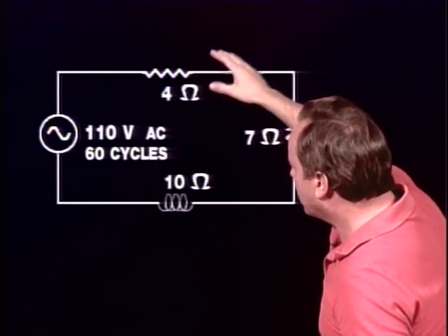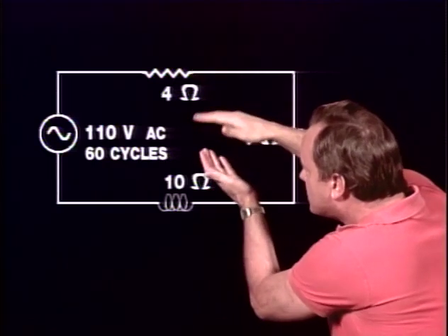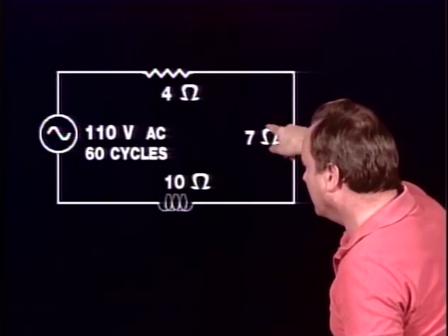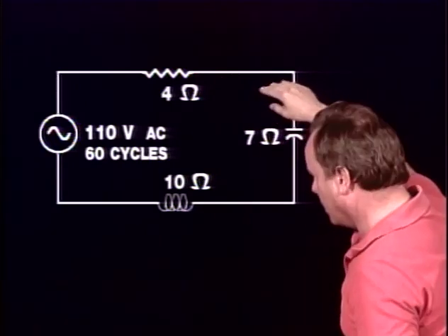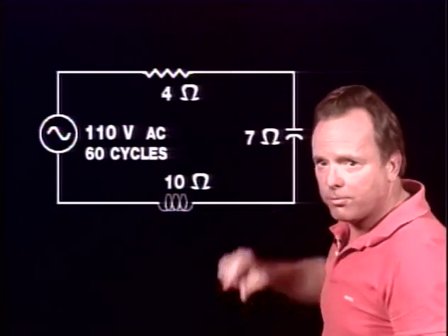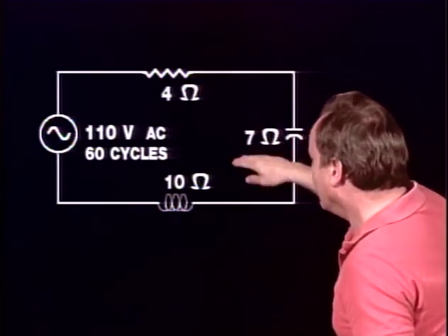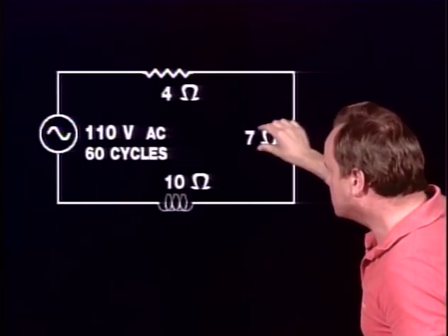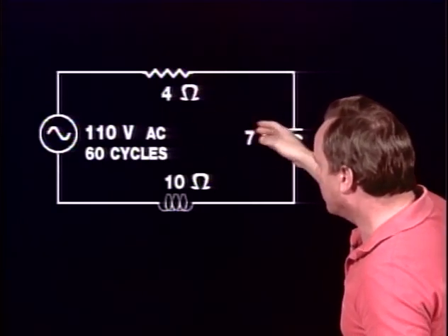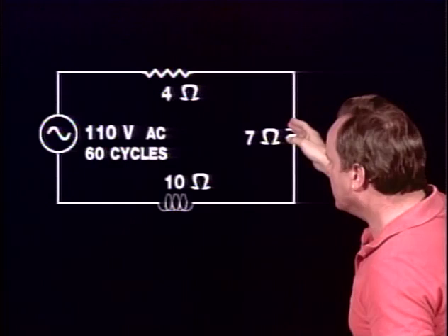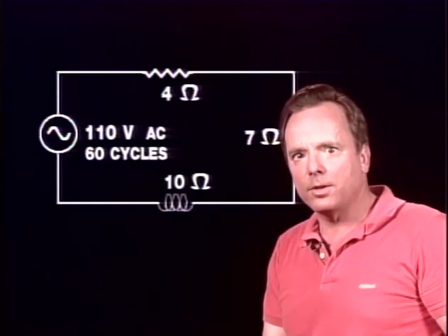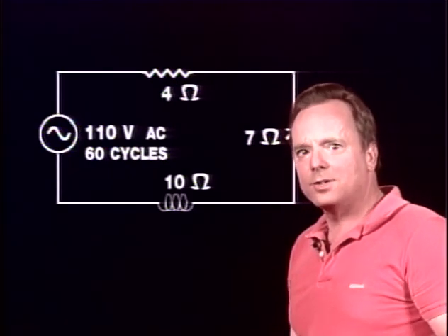But if the alternating current has a frequency to it, as the frequency increases, this capacitor tends to impede the current less and less because it charges the plate and it gives up its charge. Charges the plate, gives up the charge. And the faster the current changes in frequency and direction, in other words, the higher the frequency of the current, the less impedance is imposed by this capacitor here. And by the way, since the capacitor is almost like a short at first, it gives a place for the current to go, what happens is the current is about 90 degrees ahead of the voltage. Now in inductance, remember that the current's about 90 degrees behind the voltage, and this is going to become important.